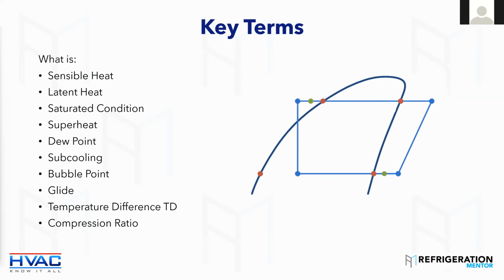Drop in your suction pressure. 100%. No oil return is suction pressure. And it's going to skyrocket that compression ratio really quickly. And that's why it's so important to understand pressure drop in your suction line. I've seen it many times, field supporting, where they got the wrong suction line. From the evaporator to the condensing unit, there's 12 or 15 PSI pressure drop. You're going to run into major issues.